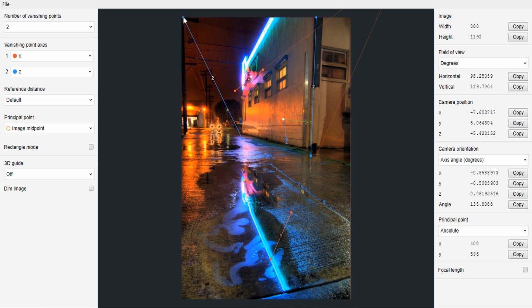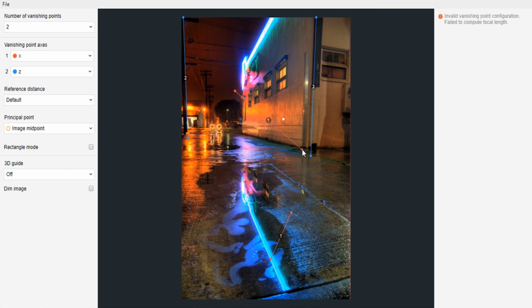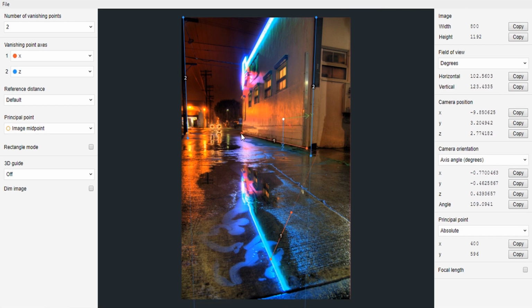Okay, so let's do that. I'm gonna put this one over here and this one right here. And for this x-axis, I would like to follow these corners. This corner over here, this bottom corner, and the one on the top. And simply follow this line on the top like this. So this is the key to use the FSpy add-on. Once you drag your reference, you simply try to find some patterns to follow, like the one that we are using here.